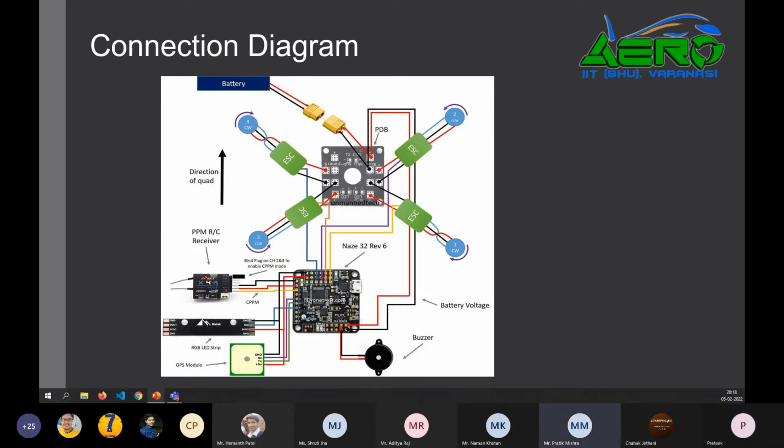No, I asked how many of these we are going to buy ready-made, and how many can we make on our own. Motors, ESCs, and power distribution boards, of course, you're going to buy on their own. Flight controllers, you can design on your own using different development boards that are available.